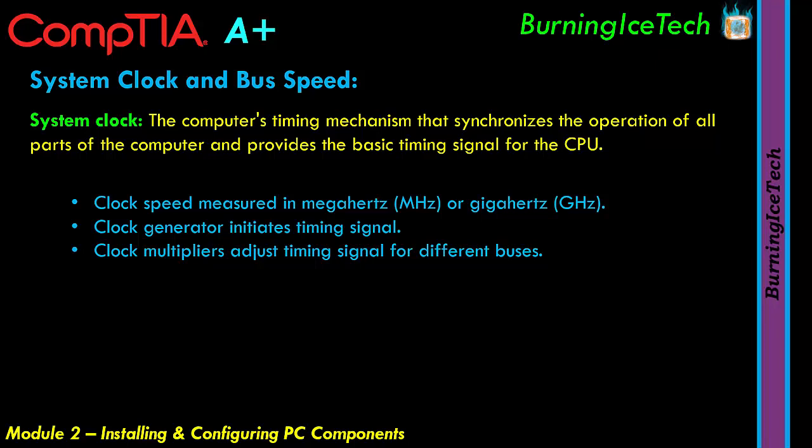You can go and do something called overclocking, which is not actually covered in this course, but it generally involves sending more power to your CPU. In a nutshell, if you send more power, that means more speed. More speed means more heat. So if you're going to do that, you need to know what you're doing. You're going to need proper cooling, preferably some form of liquid cooling. The old conventional fan with a heatsink might not get the job done then. And if you don't know what you're doing, you could push that CPU too far, and you could end up burning out your CPU or even burning the motherboard in some cases.